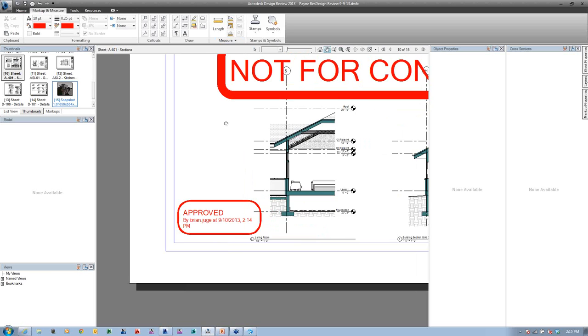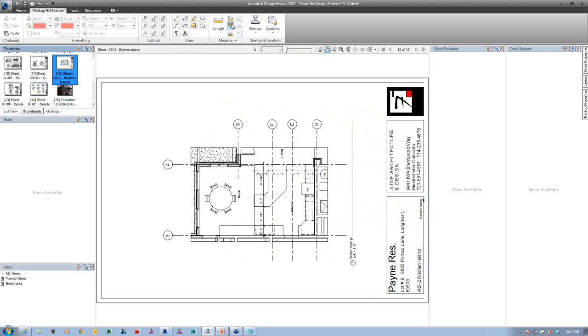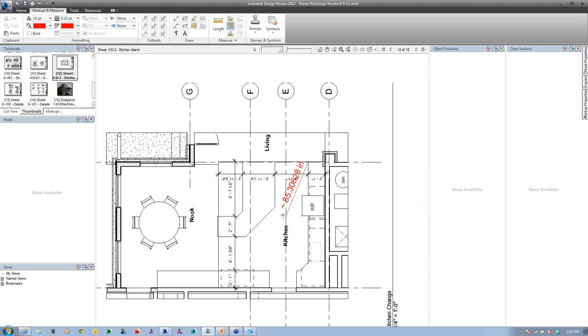We've got a way of doing links, so if you want to do multiple links, this is more for floor plans, so I'll go to floor plan real quick. Maybe I want to know travel distances. I can go in here and say, well, from this corner to this corner to this window over here, it'll give me the total distance. And I can say, oh, I need it to be a thicker line, so I just select that again and say okay, and I can start looking at the distance I'm traveling on that particular line. Or maybe I want to change the line type into a little dash line, and I need it to be a different color. So again, you've got all that flexibility of changing that out, so it's not all the same notes over and over again when you're looking at this.